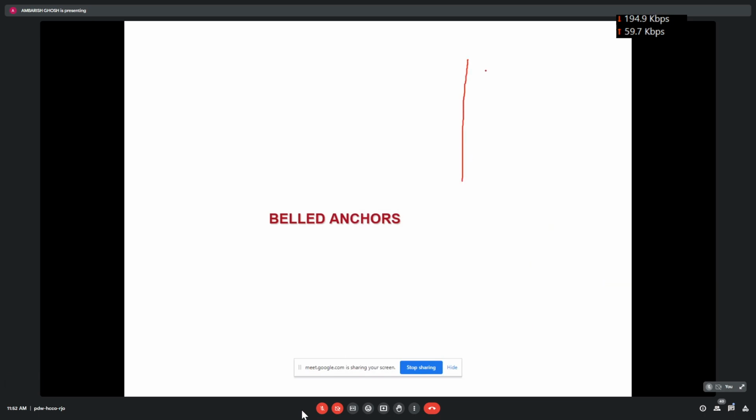Sometimes piles you will see are made like this, mostly in expansive soil, where you go for what is called a bell.